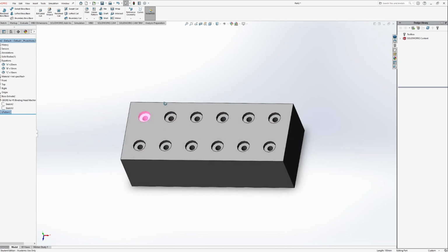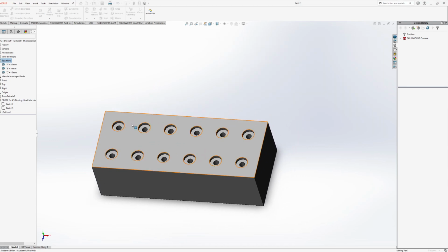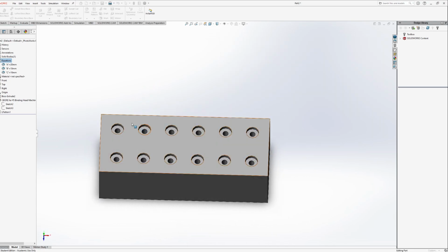Now, here's something that's actually kind of cool. Let's go back into our Manage Equations tab. So right click and then hit Manage Equations on that equations folder. We're actually going to see some extra stuff that's populated here now, specifically in the equations drop down. And all of these equations here are going to be the ones that we utilized when we were just dimensioning this in general. So what's nice is that we can also add equations from this tab as well.